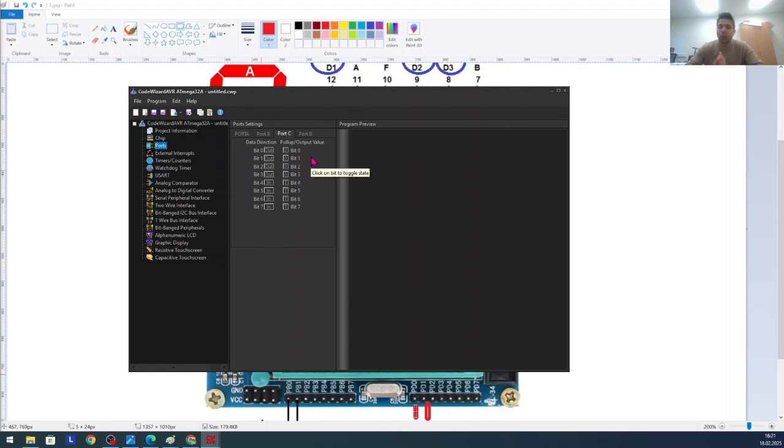In general, when we are not using the pins, we should leave them as the default, which is input. Because if you leave them as output and by accident you connect them to ground during the work process, a huge current will pass through the microcontroller and it will damage it. That's why it's safer to just have them as input if you are not using them.